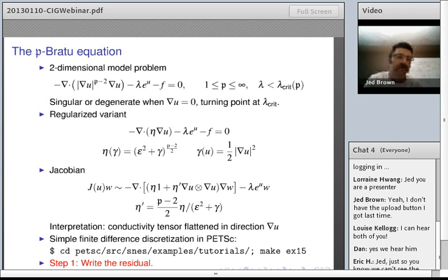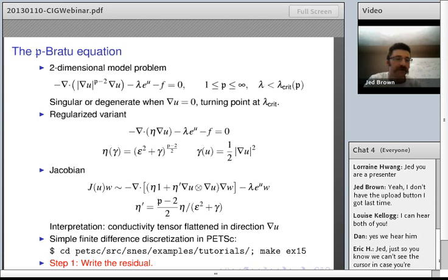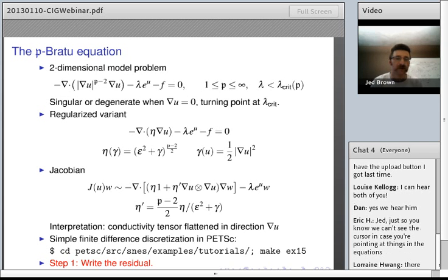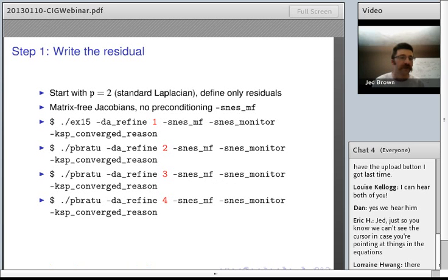For more advanced solvers, we'll spend a lot of effort in operations related to matrices or related to multigrid, but the first step should always be to write the residual. And that should be very comforting because you write it once, you'll verify on small problems that the residual was coded correctly, and then you never need to worry about correctness. So we can write the residual and not write anything else.